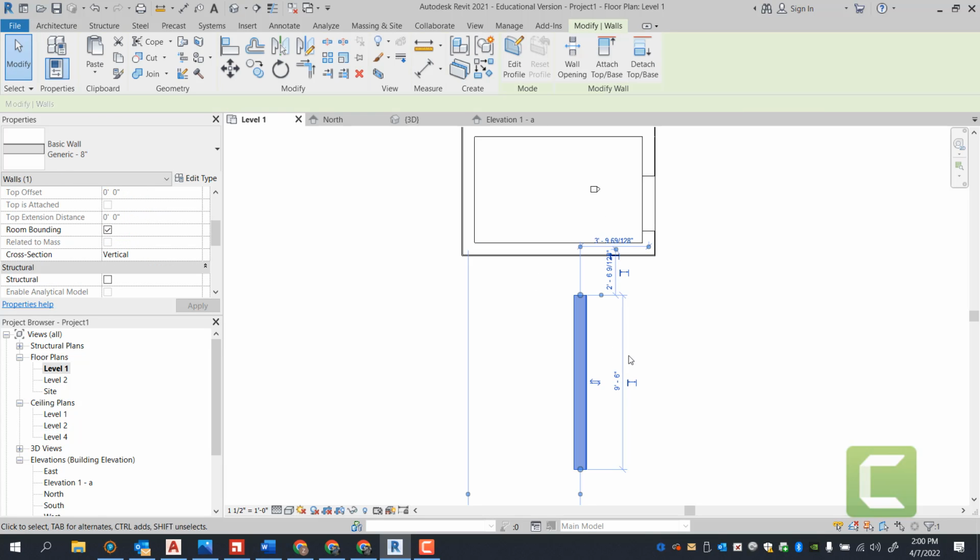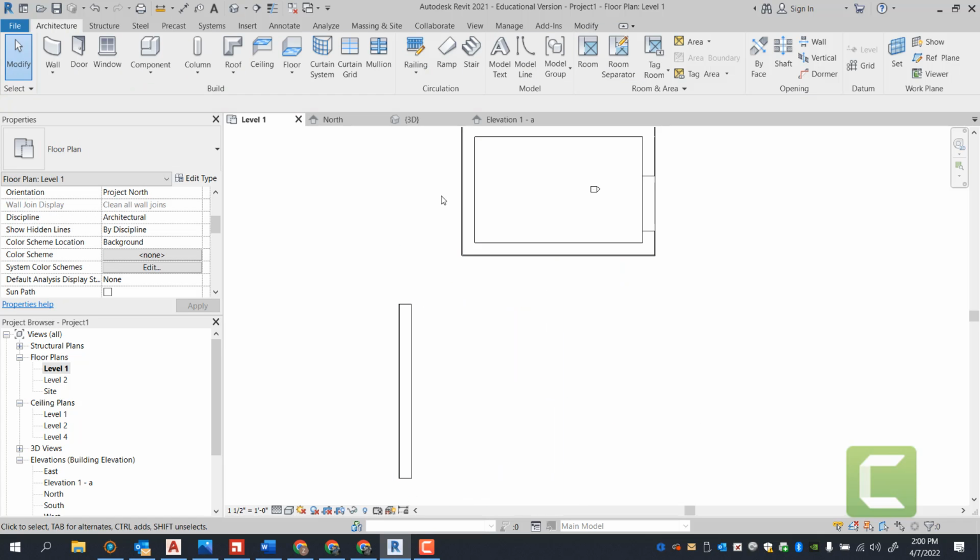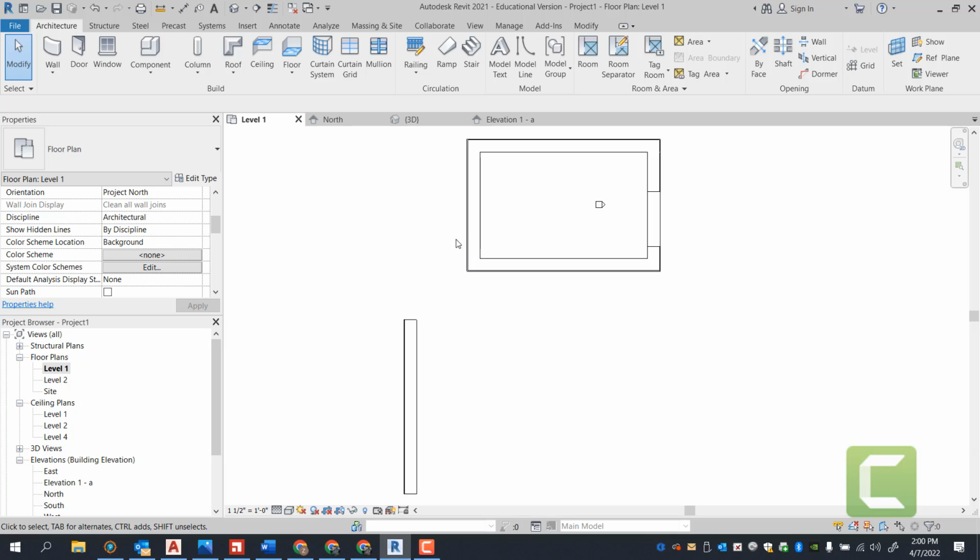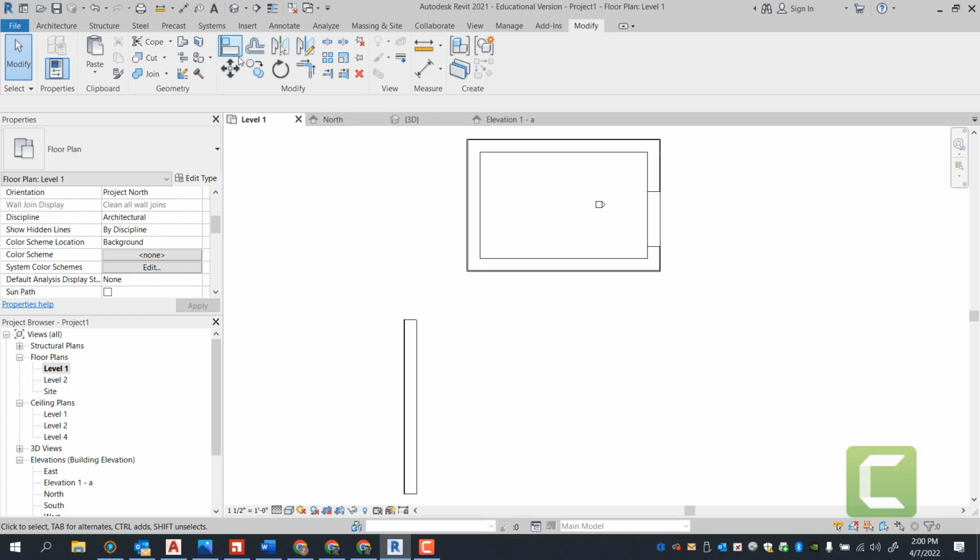Align. Align is very simple. All you're doing is, let's say I have a wall here, and I have something here, and it asks you to align this wall to this. You will type in AL, which is the shortcut, or you go under modify, and of course they have the same shortcuts here. Everything is 2 letters.